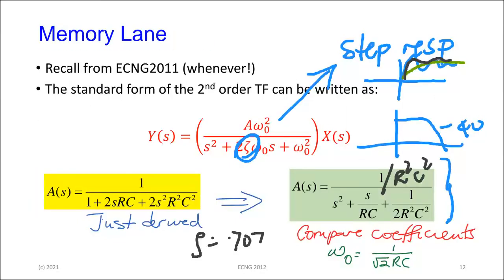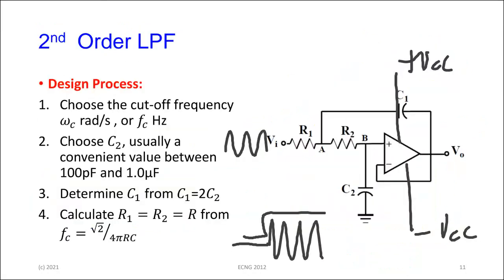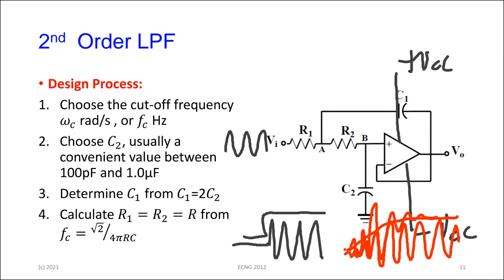That step change, because of the behavior of the second order system, as it goes through the amplifier, let me backtrack here a little bit. As it goes through the amplifier now, if you have that step change, it means that the output, instead of doing whatever it's going to do, may do this and then settle to whatever it's supposed to do. Remember, that is critically damped. So if it's slightly underdamped, it might go up a little bit and then settle down. So the output might do something like that.